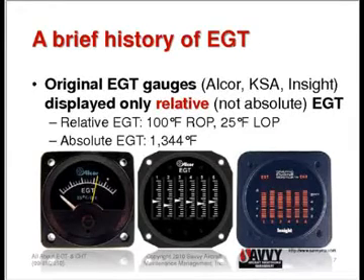We leaned to a peak value, and then we could enrich or lean to bring the EGT down a certain amount from peak. And very similar to the analog gauges, each little segment on these digital bar graphs was worth 25 degrees Fahrenheit. So although the display was more sophisticated and the software did some fancy things like lean find and all that stuff, we were looking at relative information only when it came to EGT. This turned out to be a good thing.